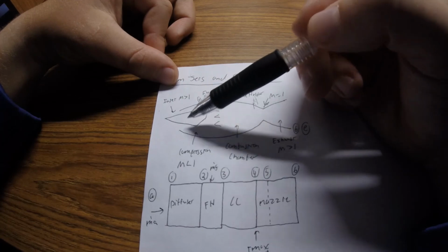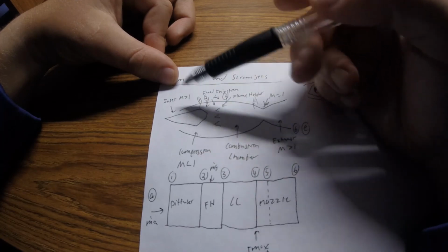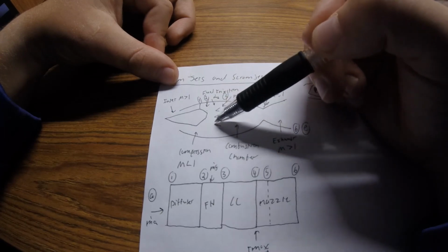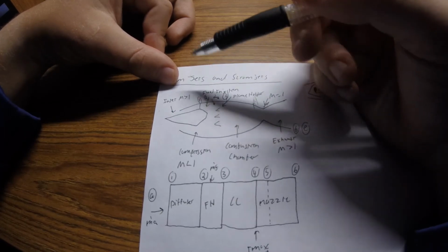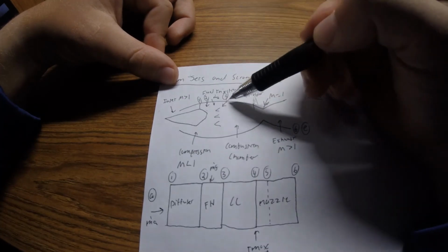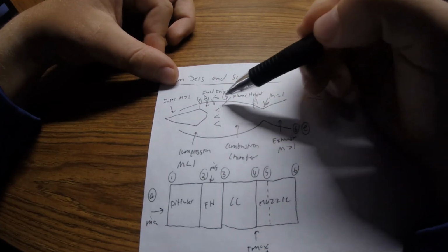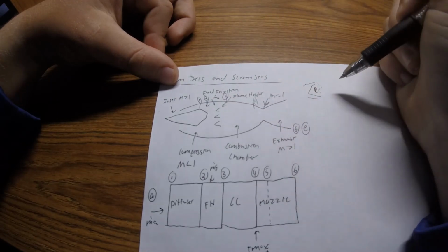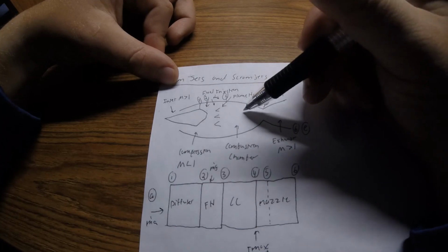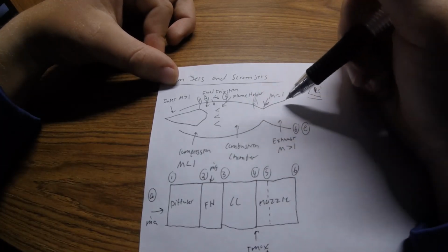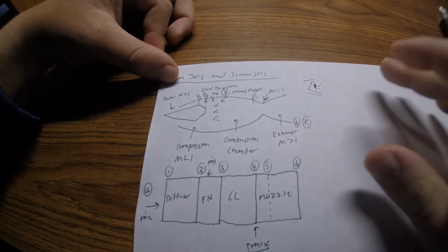The speed decreases through the compression, kind of expands back. Temperature stays the same, pressure decreases. It gets mixed with the fuel, gets lit on fire, then it accelerates back out the nozzle, gets much hotter, hottest point right here, and then goes out the back of the nozzle.